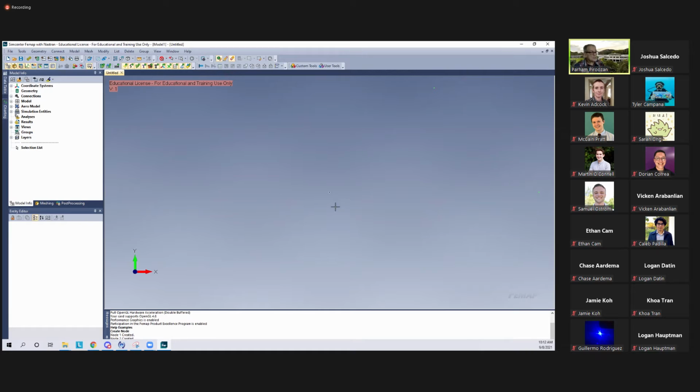On your screen, you see actually these dots which I created. I see one of them here. Let me see what I created. So I'm pressing the Control and the left mouse button to drag it down here. You see actually 3 nodes, 1, this, and this. A very light color is difficult to identify them. So let's have the node numbers written. I want to show the node numbers, to make sure I have done it correctly.